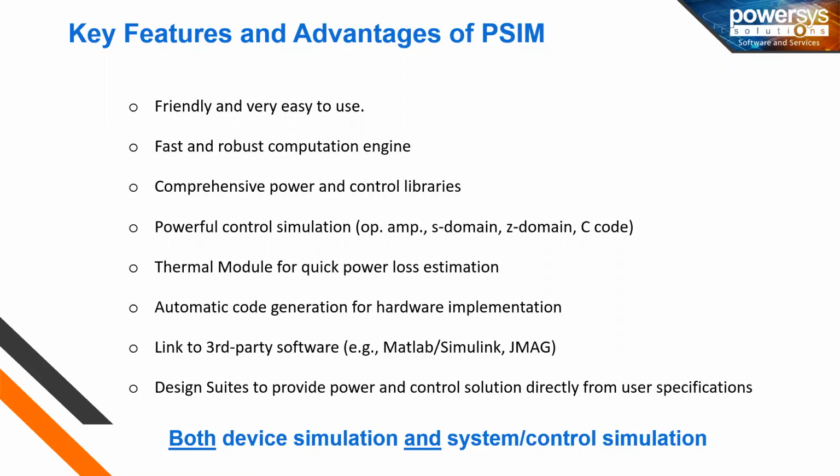You can also use our thermal module if you want to scan the curves from the datasheets of your MOSFETs or IGBTs, for example. At the end, you can directly calculate the losses of those IGBTs, MOSFETs, inductors, and diodes, depending on the curves from the datasheet. The losses will be quite accurate because if you use the datasheet in a proper way, the losses will be calculated according to these curves.